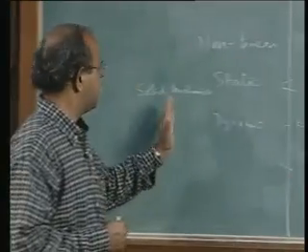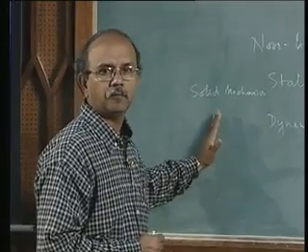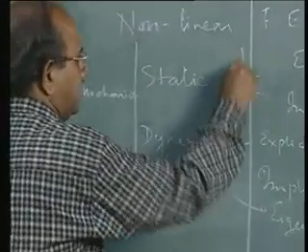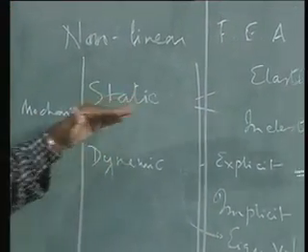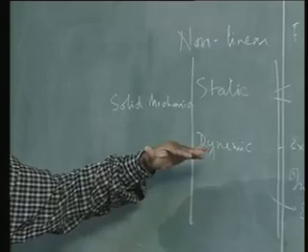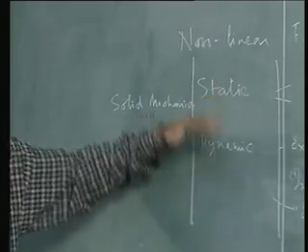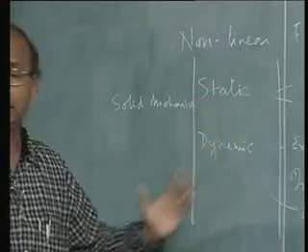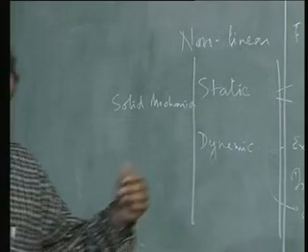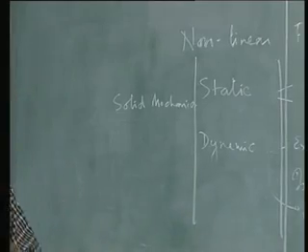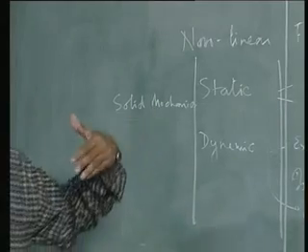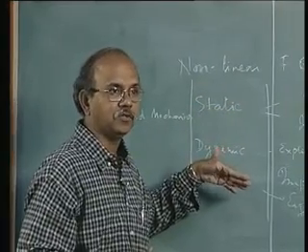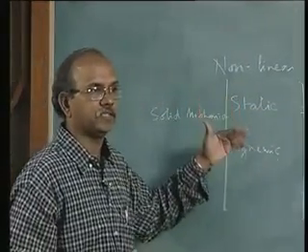But once we decide that we are going to do a stress analysis problem, the first thing we have to do is to recognize what is the type of analysis. So whether you are going to do a static analysis or whether dynamic analysis, that depends of course on the problem. That's the first thing that we have to decide. Now it's not a very easy decision. Many times certain dynamic analysis you may have to simplify using static analysis, and many static analysis problems can be very easily done using dynamic analysis. So it is not that it's a very straightforward decision many times.